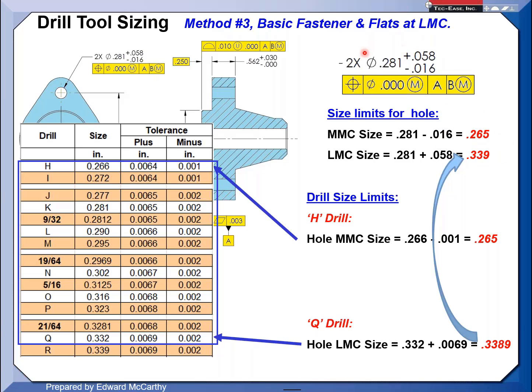But now, I've seen sometimes more with tooling designs, or my tooling fixturing people, they'll sometimes lean toward what we call unilateral. They're leaning more one way, they would prefer to see a part. So again, that's a design intent, but to answer your question, no, you could have easily done an equal bilateral here. I just said, no, don't do it for this case, just to keep the answers at a minimal.